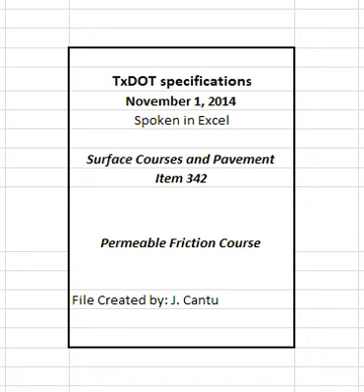Furnish CSS-1H, SS-1H, or a PG binder with a minimum high temperature grade of PG 58 for tack coat binder in accordance with Item 300, Asphalts, Oils, and Emulsions. Specialized or preferred tack coat materials may be allowed or required when shown on the plans. Do not dilute emulsified asphalts at the terminal, in the field, or at any other location before use.